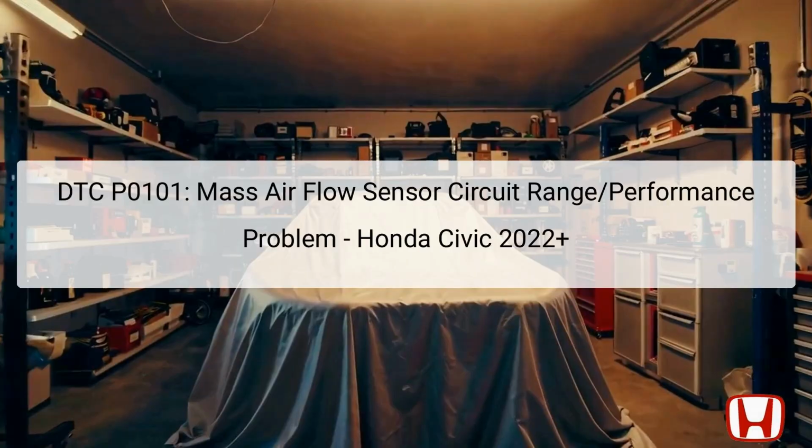The DTC P0101 is a diagnostic trouble code that indicates a mass airflow sensor circuit, range, or performance problem, specifically for the 2022 and later Honda Civic models. The mass airflow (MAF) sensor serves a critical role in ensuring that the engine receives the correct amount of air for optimal combustion. It measures the volume and density of incoming air, sending vital data to the powertrain control module (PCM) to adjust fuel delivery as needed.